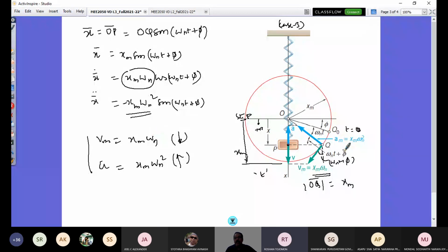Yes, sir. Thank you. So how do you define a simple harmonic motion? It is the projection of a particle which is executing a uniform motion on a circular path, and its projection on its diameter. So if Q is the particle, and it is projected on its diameter, then it is P. So the motion of P is what is now simple harmonic motion. And this Vm is going to be constant. That is why you have this natural frequency constant and xm radius is constant. And this auxiliary circle is helpful for us to understand simple harmonic motion.